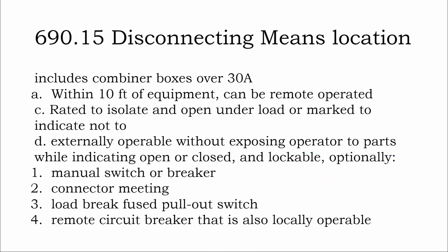When I'm buying a disconnect switch, it might be cheapest if you're just doing a simultaneous disconnect of each 120 volt pole. It's probably cheapest just to buy a 2-pole non-fused disconnect switch. I've usually regretted buying a 2-pole switch instead of a 3-pole switch to also disconnect the neutral, because you don't have to disconnect the neutral.